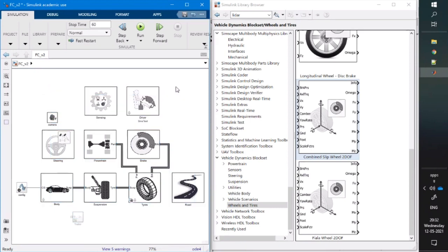And regarding the spatial contact block that I mentioned previously, be very cautious. It does not directly work with CAD models. So when you're using that, be cautious. That is the reason I purposely used the primitive blocks within Simscape only. I could have used the CAD models, but CAD models do still have some issues. I think they will be upgraded in upcoming releases. So keep an eye on that.